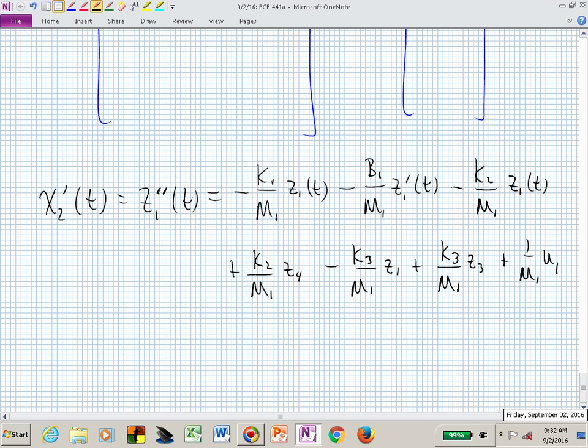And that's all from that second order differential equation, from the free body diagram for mass 1, and I've simply multiplied it out, distributed all of the terms so that I now have each one individually expressed, which now allows me to combine like coefficients for the like factors of z1, z2, etc.